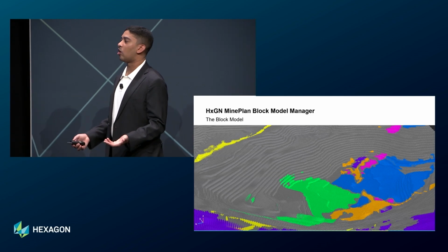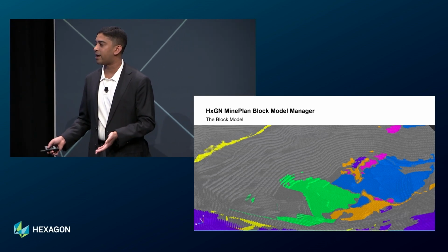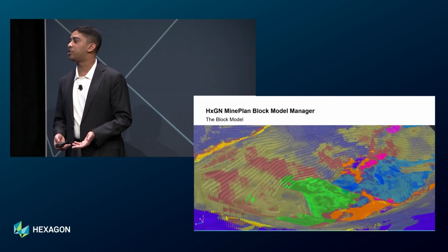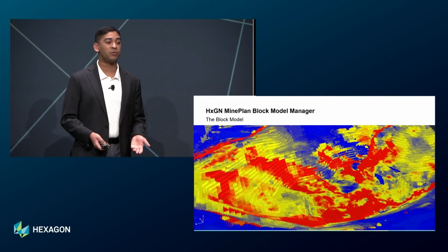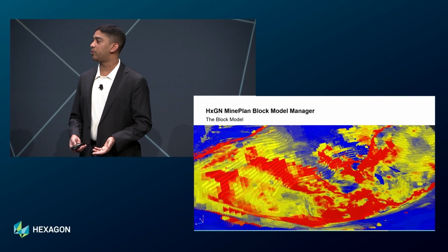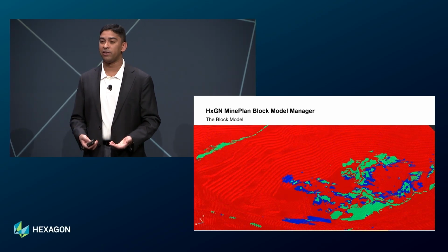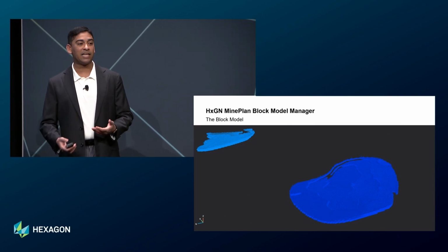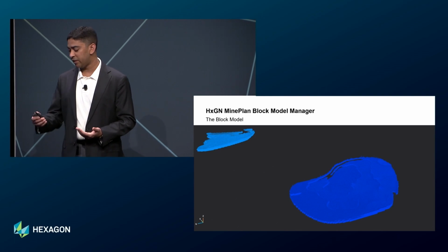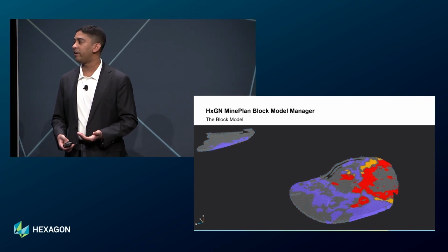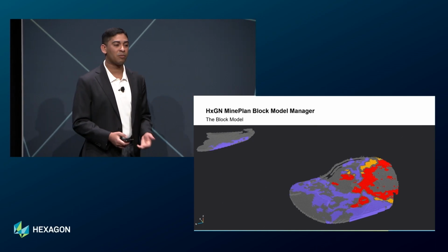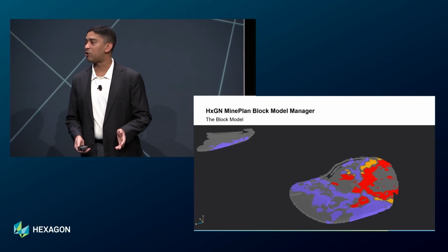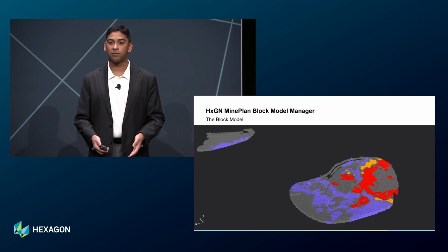So just as an example, this is a block model from one of our client sites. We're storing the geology, and within that geology, we get a feel for what the grade distribution is. This grade distribution is helping us calculate a value. And from this value, we're determining what the ultimate pit is, and it gives us that life of mine. And then from there, in a shorter term horizon, we figure out where that material should be sent. So what stockpiles, directly to the crusher, to the waste dump. That routing decision happens as a result of what's in the block model.